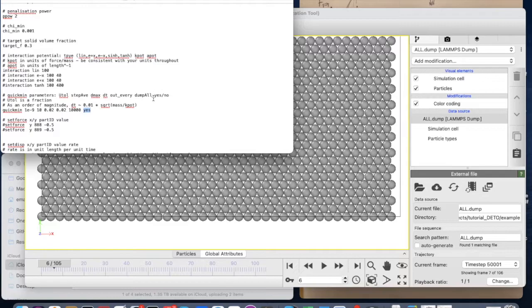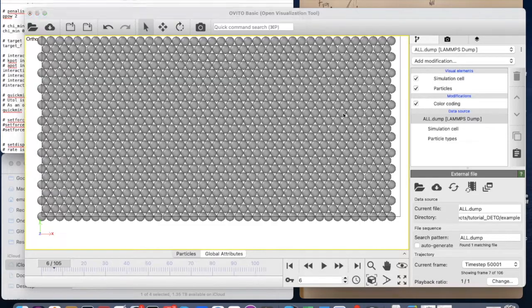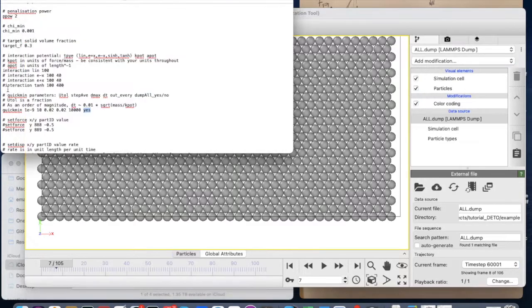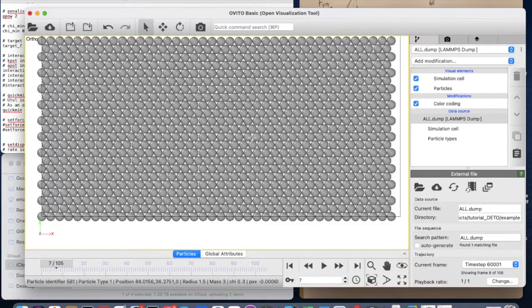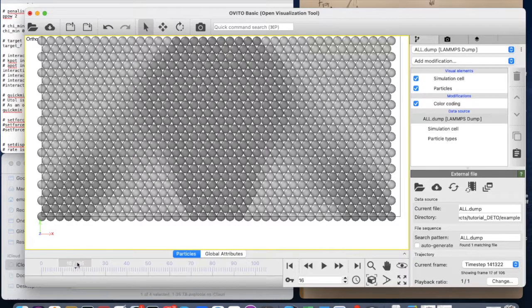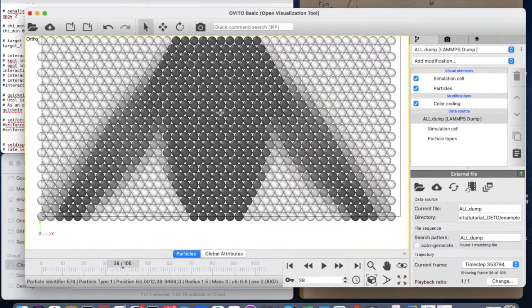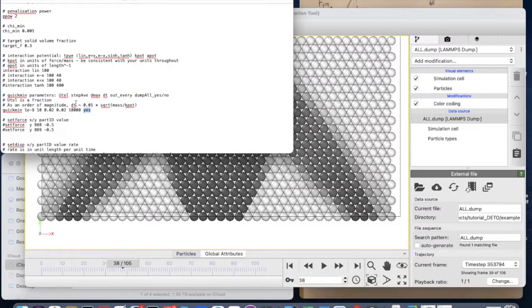Finally, yes or no here: this tells you whether you want to create files that you can visualize in this way for all the steps during the simulation. Usually it's good practice to keep this as a no, but there are some situations where you want to put it as yes. For instance, now I want to show you the deflection of a beam in between the different steps of the optimization, when the design is fixed and we are looking for equilibrium. And so just to show you this, I take this to be yes.